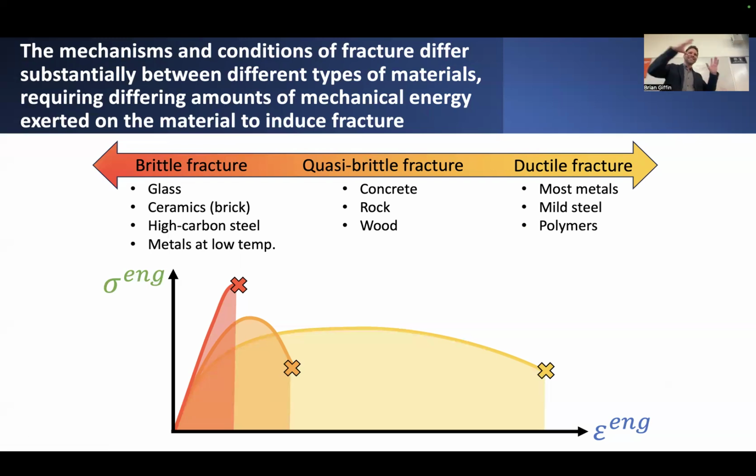It's kind of like, there's definitely some non-local dissipation and damage happening in the material close to the crack tip, but it's certainly nowhere near being characterizable as ductile fracture. So really different mechanisms also govern how these processes evolve. Certainly in concrete or other types of cementitious materials, the mechanisms for how the material separates will look different, at this mesoscale, compared to what it would look like for a metal.